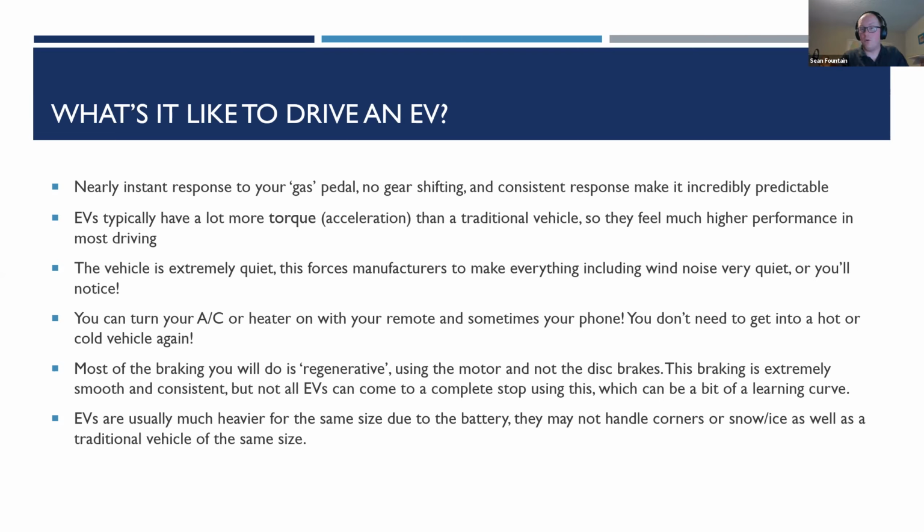And when you're going around corners and you can lose traction, like ice, snow, wet conditions, an electric vehicle, you'll feel it, is a lot less sure-footed than a gas vehicle. You can throw tires on it that are a lot more sure-footed, but you'll lose range because those tires stick to the road a lot better, and so it has to work a lot harder to roll them.